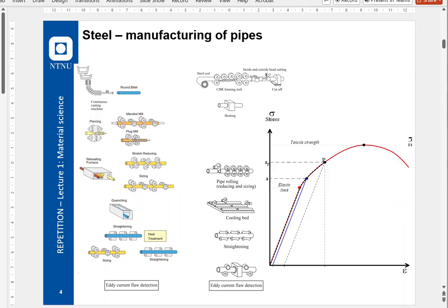One thing that is essential for us is the yield point of steel. We see the stress strain curve to the right. We talked about that part, and we said that point A on the stress curve is the yield point where you have 0.2% permanent deformation, and that's very often the design limit in casing design. Why?